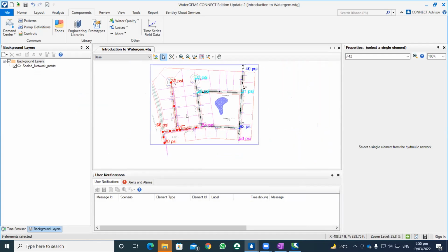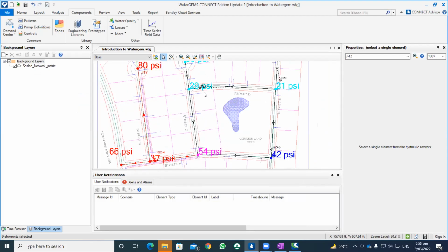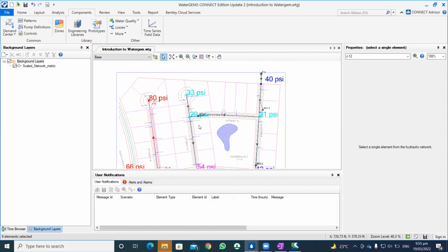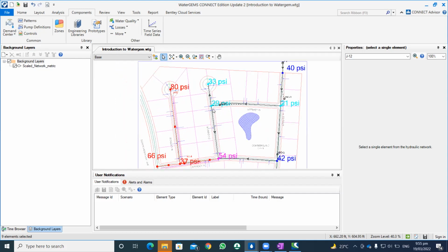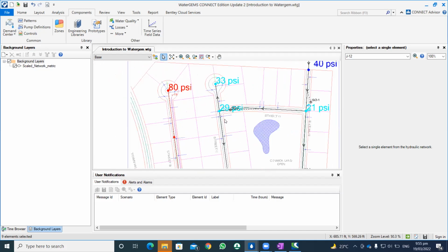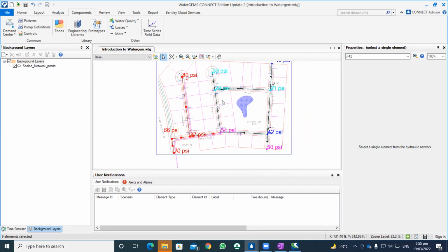So basically in designing, you will have to plan how and where to insert these different types of isolation valves, and you cannot install isolation valves at each node or near each pipe and junction, because of the economics, the funds available with the client.